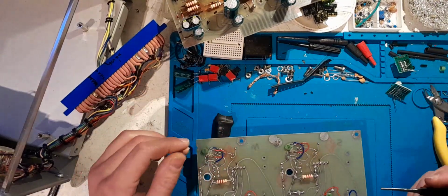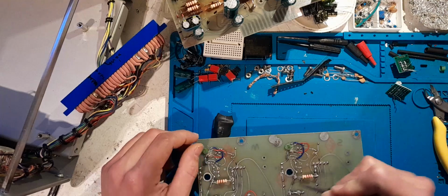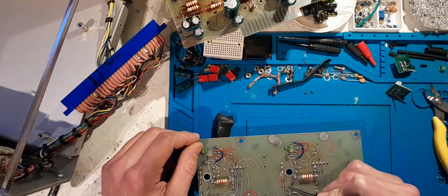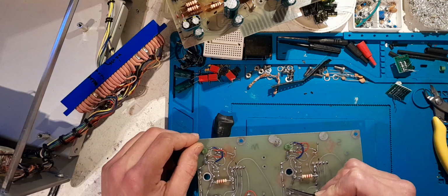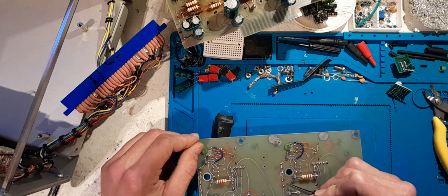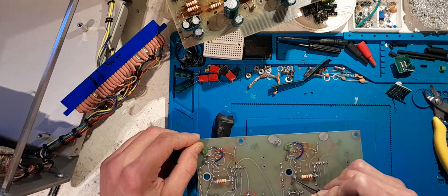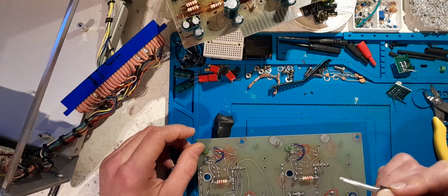I'm going to take the TL431 out. I'm going to sit it basically sideways, so that one pin there, one pin there, one pin there, more closer to there really. And then I can run one pin over to one track, like the cathode, the anode over to the other track, and then the reference up to the wiper of the pot, and then one of its pins over again to the track that the anode and the track that the cathode's on.